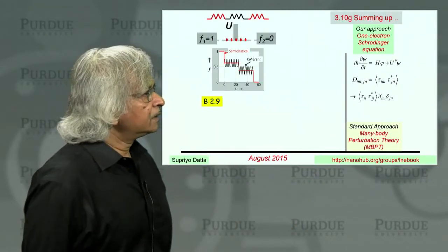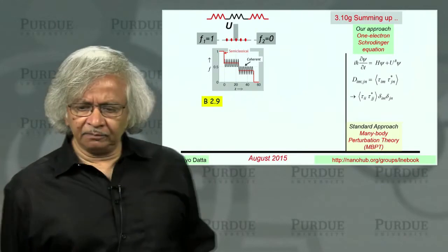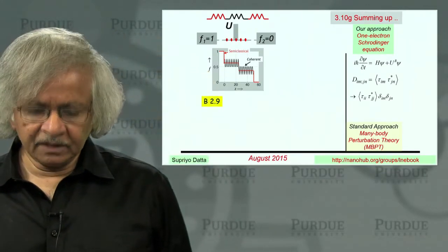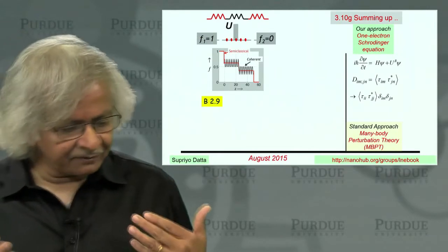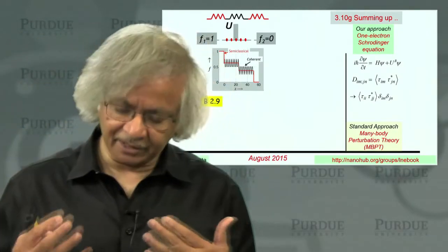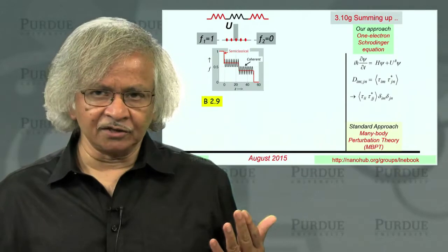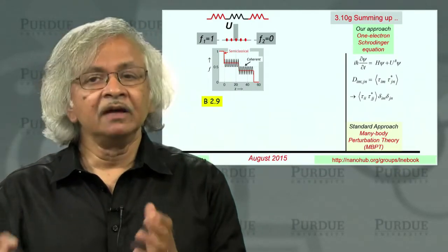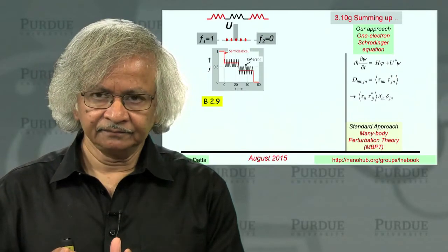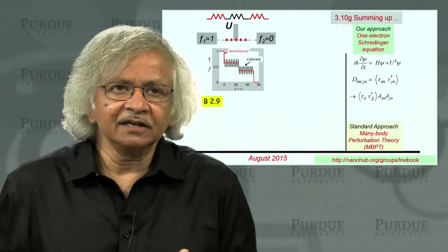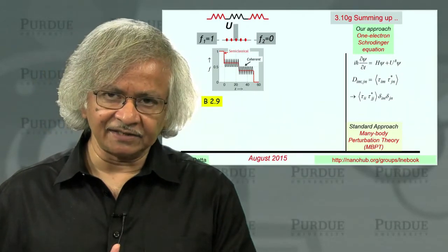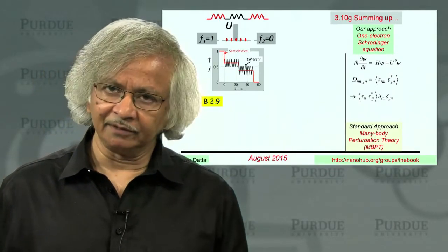Now, one important problem that often people worry about is this electron-electron interaction. As I mentioned, this is a very subtle kind of interaction where momentum is not relaxed, because what momentum one electron loses, another picks up, but phase is destroyed. And often, standard conductivity or mobility is not affected by phase relaxation, it's only affected by momentum relaxation.